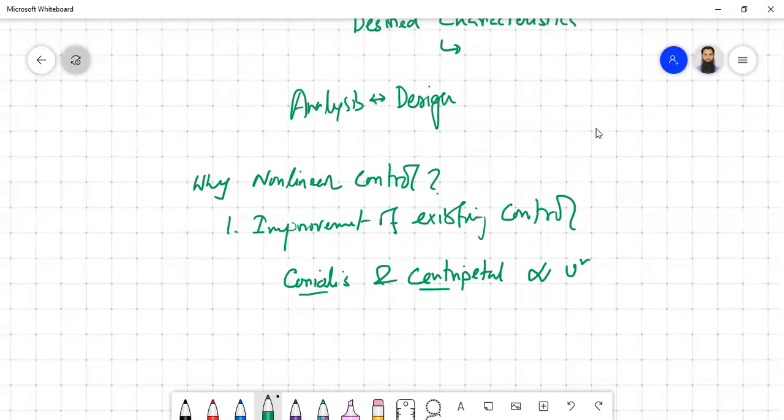In that case, the system moves away from the control technique more. It will deviate more, so it will give us less precision in the output. Take tasks like pick and place, welding, or laser cutting. Basically we cannot increase the speed. If we increase the speed of the processes, these forces increase, so our output becomes lesser and productivity also reduces.